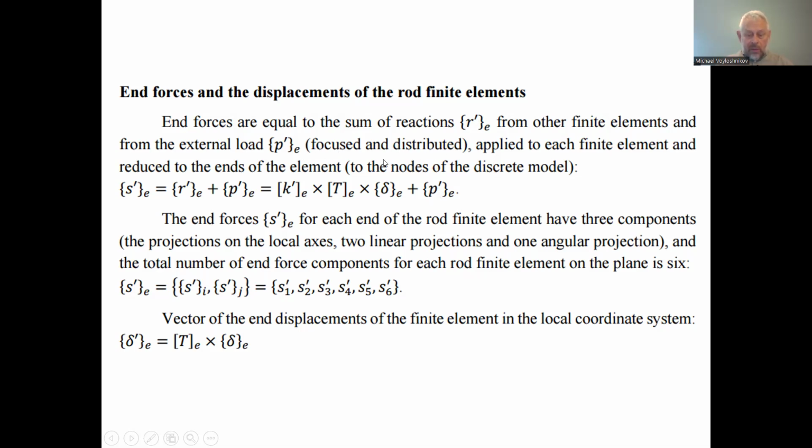The concentrated external load acts at the nodes, but there is also the load acting within each finite element. The end forces S stroke e for each end of the rod finite element have three components: the projections on the local axes, two linear projections and one angular projection. And the total number of end force components for each rod finite element on the plane is 6.